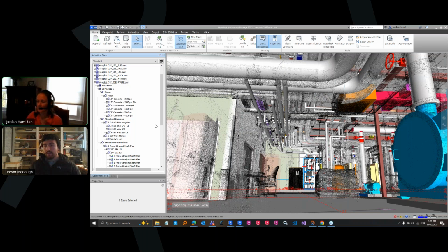You can see that the Navisworks selection tree system, this hierarchy here, is very robust. There are hundreds of thousands of items here. But if I'm only interested in analyzing the steel I-beams that are on level 2, or only need to verify the location of the hot water pipes, I could click through Navisworks and start building a selection of only those objects.